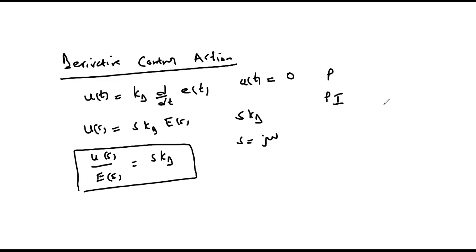In summary, we notice that the derivative control action has an anticipatory capacity to correct the error, and its shortcomings are the possibility of amplification of noise, and that we cannot use it when the error is constant. And those are the advantages and disadvantages of the derivative control action. That is the end of my discussion of the integral and derivative control actions as used in control systems.